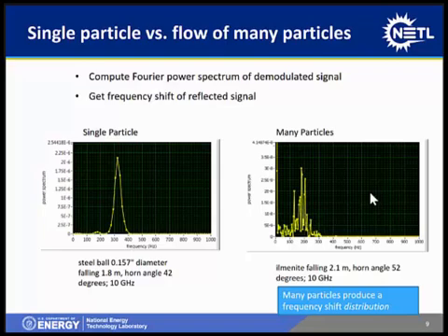If we have multiple particles, they enter the sampling domain at different times. We get interference between the different individual reflections, and we end up with a spiky-looking spectrum, but we still nevertheless see a peak at a frequency that corresponds to the average velocity of those particles.